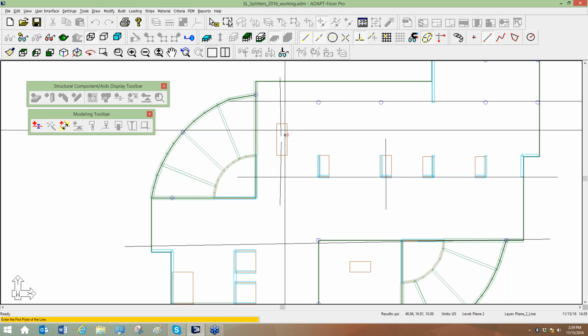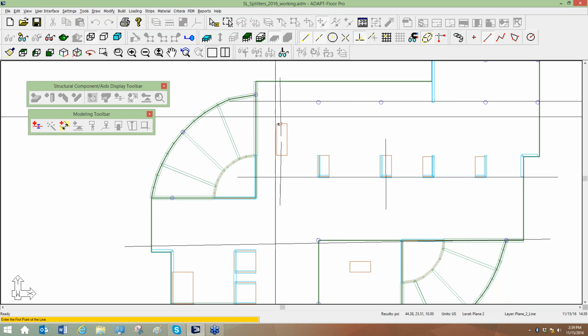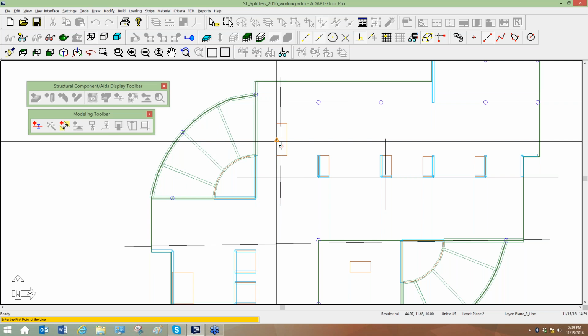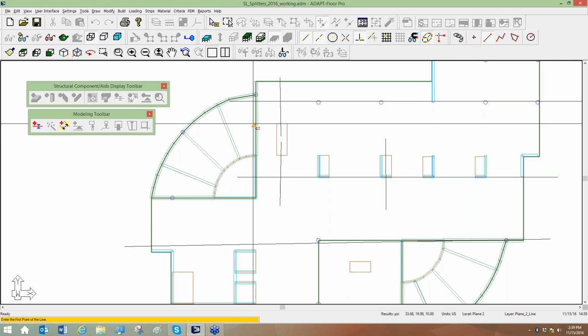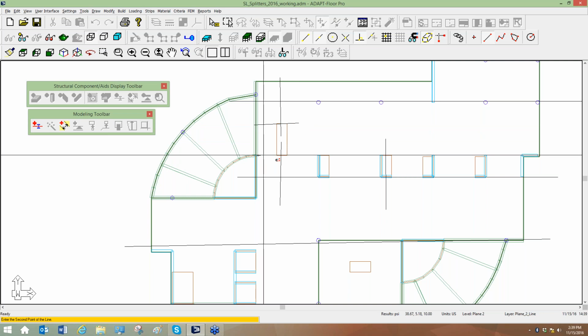Even though the design cuts extend into the opening, there's no concrete there, and that means there's no shell element there. So it cannot obtain a value where there is no shell or node, and it's basically just a void. So graphically it shows the cut extending into the opening, but in reality it's acceptable because the integration really stops there and it stops right there.